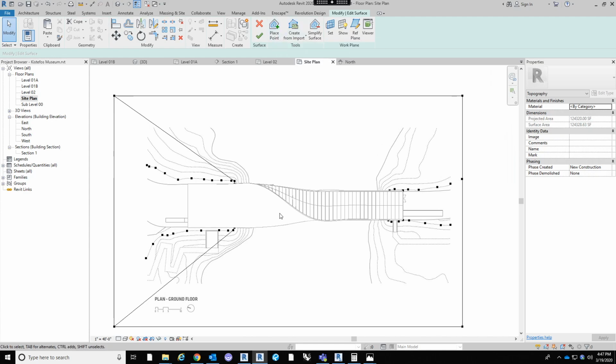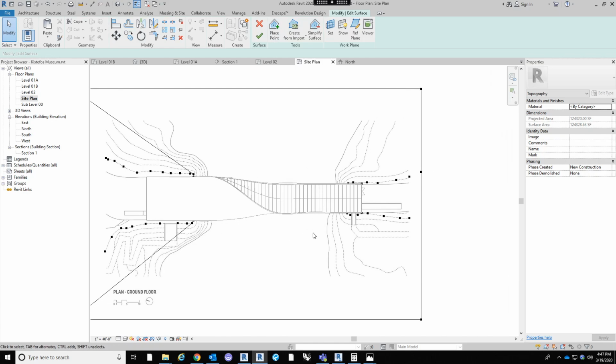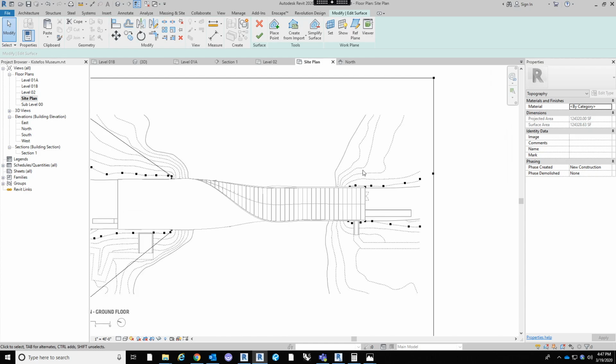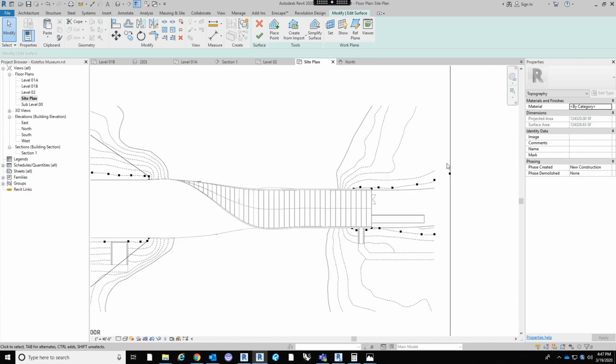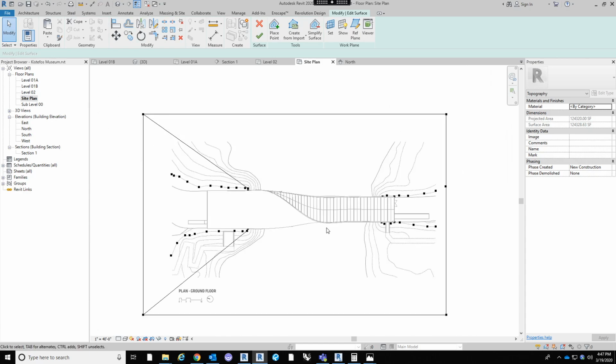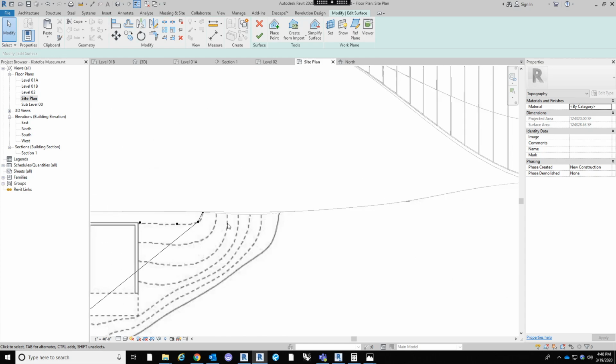Now we'll create the grade in the middle, or in the center. Create the slope down to create the river. And so what we'll do, you can draw individual elevations at each contour line, or you can skip. So these are probably in meters, so I'll just do it real simply as 3 feet increments.